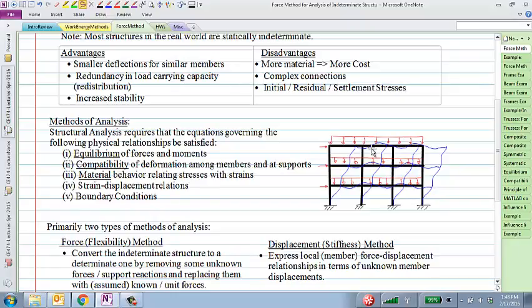In fact, one way to think about indeterminate structures is that if I take a vertical cut right here, and right here, and right here, it's like there are these four sets of columns, and I'm cutting them, making them all independent. Each of those independent structures is now very similar to a cantilever beam or cantilever column, which is determinate, right? So when I make a cut through this beam, how many new unknowns have I introduced?